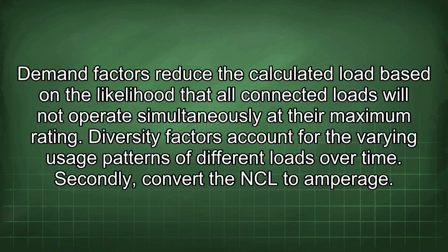Demand factors reduce the calculated load based on the likelihood that all connected loads will not operate simultaneously at the maximum rating. Diversity factors account for the varying usage patterns of different loads over time.